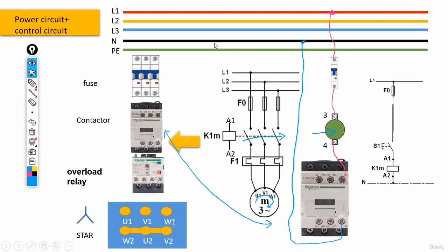Well, the electrical symbols that we have in a diagram representing control circuits would be this. There's phase, fuse, then the start push button, A1 terminal and the contactor, A2, which is connected to the null. And basically, guys, in an electrical diagram, we can find these symbols, most specifically the symbols representing control circuits, next to the symbols that we have for power circuits.